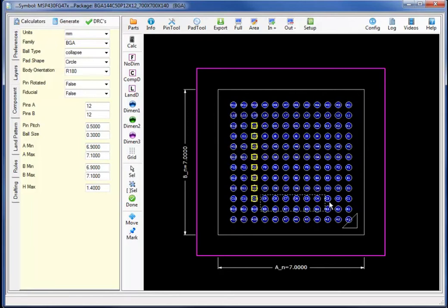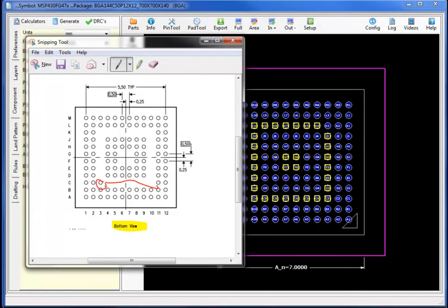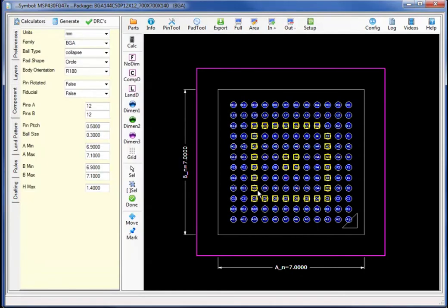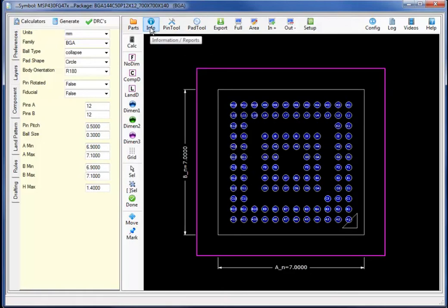I will now select a set of pins to become non-propagated. Completing the outer rows, I will now select the set of inner rows. And going back and referencing the PDF document, I will notice that the C3 pin is propagated in the array. Making the last two changes, I will move to the pin tools, where I will change the propagation to non-propagated for the selected set of pins.